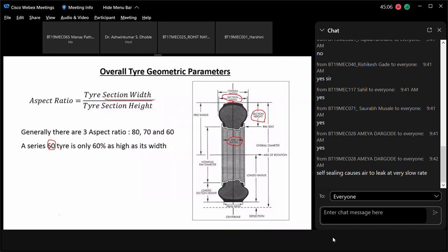So black color part is the tire. This part is basically the tire treads. Please remember that these parts are basically tire treads, and there is some protrusion on the tire surface where you check the tire linear and radial runout. Okay, this is the tire which is in contact with the road. That is why it has bulged a little bit compared to the tire which is on the top.